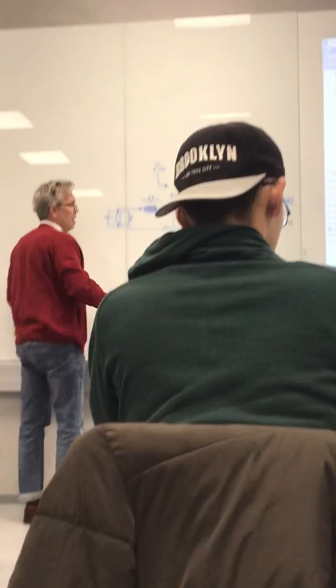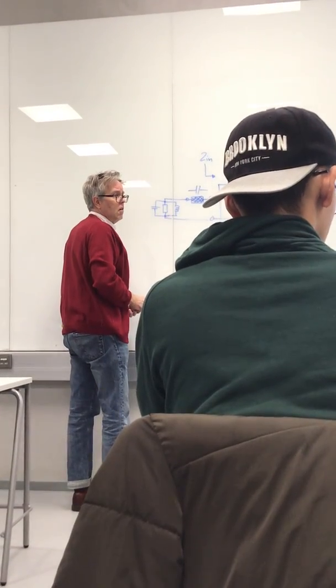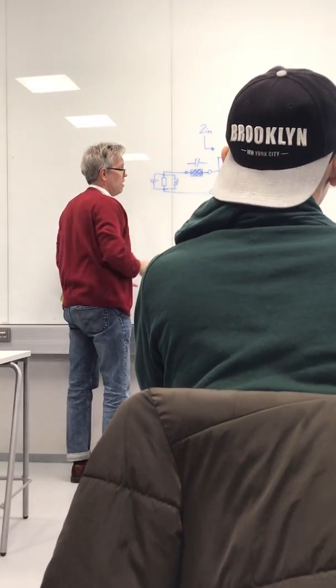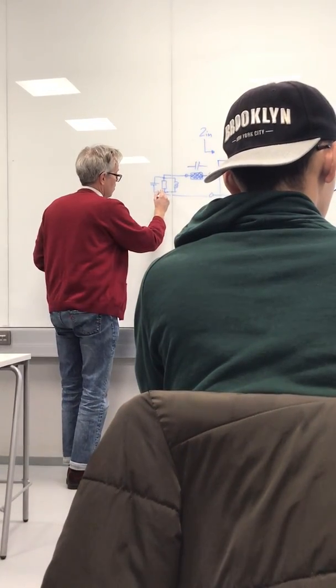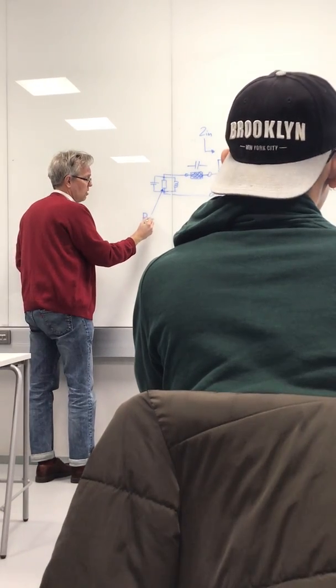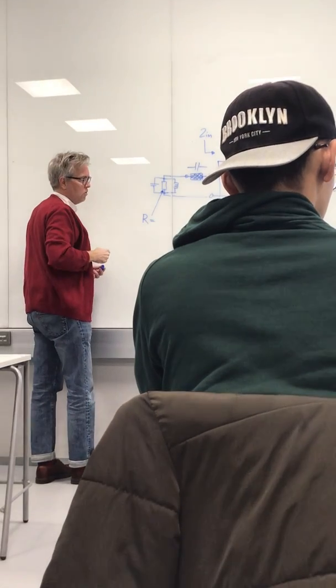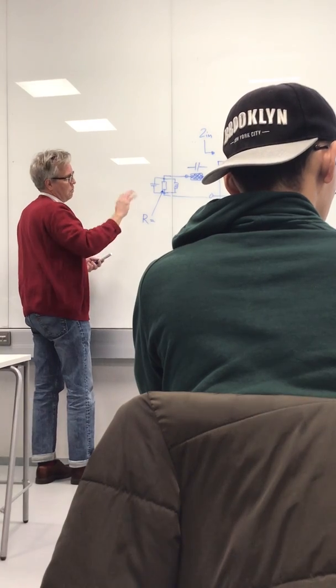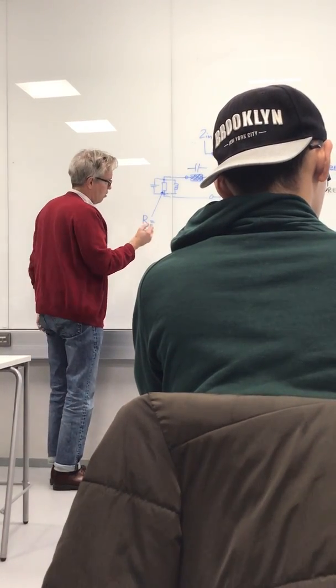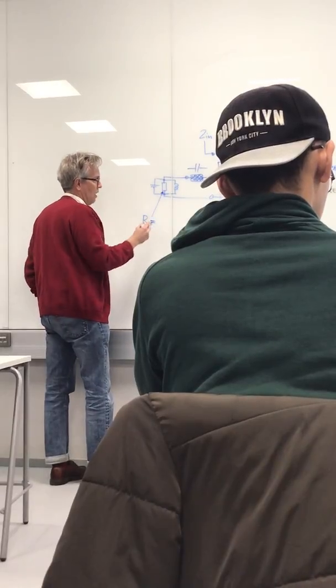We compensate the reactance part of the input impedance with the serial component. Then this resistance, which is the resistance part of the resonator, let's assume that it's done by lumped elements, which isn't true in many cases, but let's do it with lumped elements.